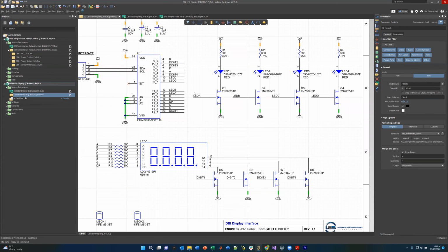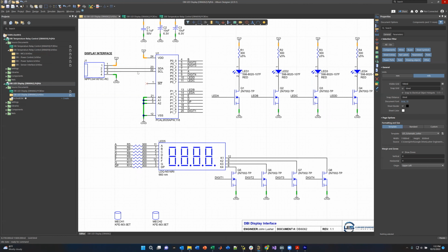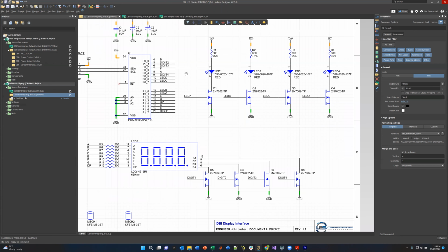I squared C is a 2-wire digital communication bus, chip-to-chip communications, and it has a clock which is coming from the master, or in this case the main microcontroller, and the slave, which is this chip here, and it just receives the data and does what it's supposed to do, which in this case is provide 2 8-bit I/O lines, and each one of these I/O lines can be either input or output. I've got them configured in code to all output, and it drives this entire board. So I send serial data over these 2 wires, and I can control all of these LEDs. So that's what's happening here.